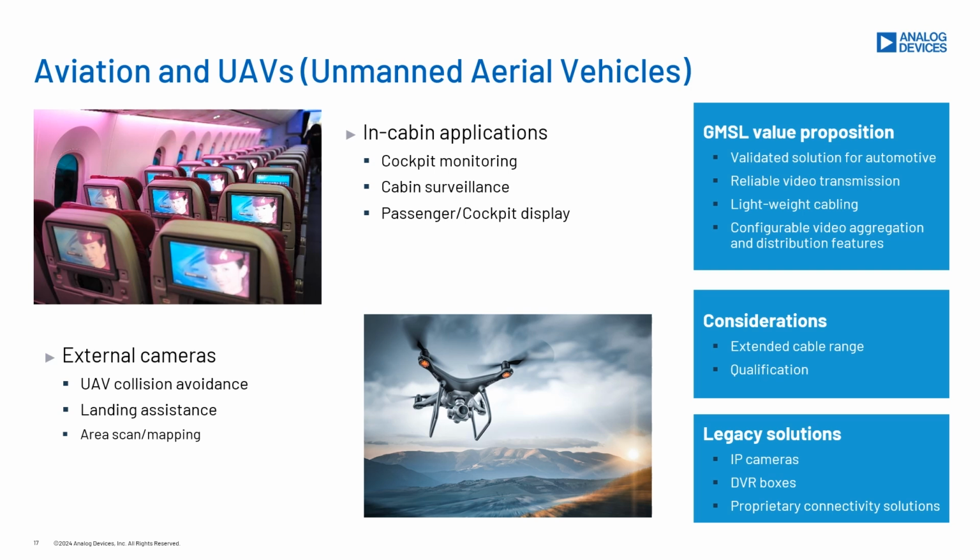For these applications, our success in automotive market gives people confidence for GMSL's reliability, including low bit error rate video transmission and system-level mechanical reliability. Lightweight cabling is also a big benefit. For some highly integrated solutions, GMSL's configurable video aggregation and distribution features also make the system architecture easier.